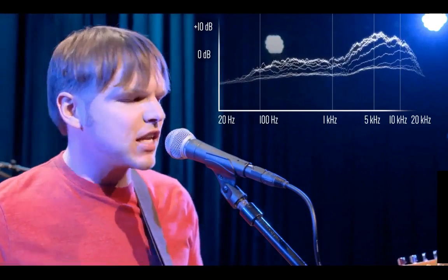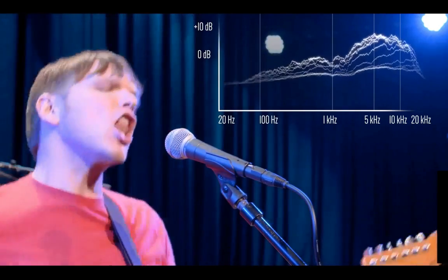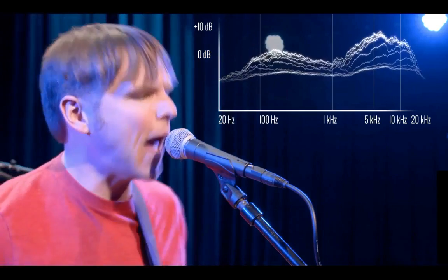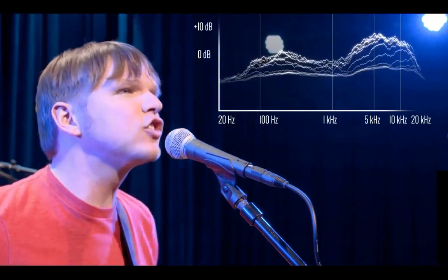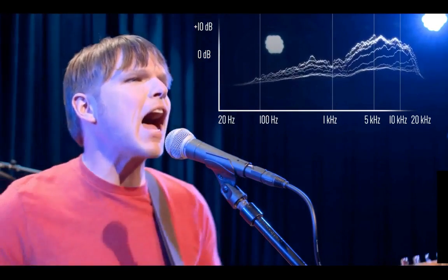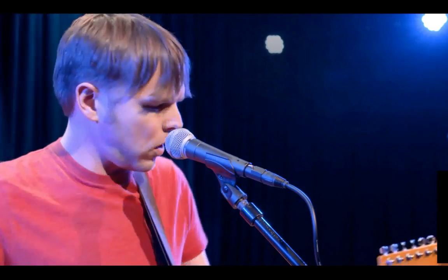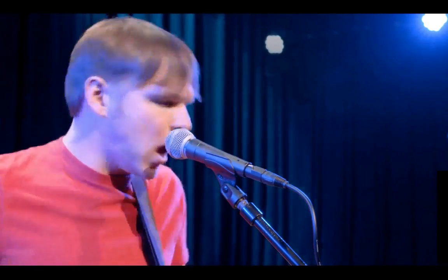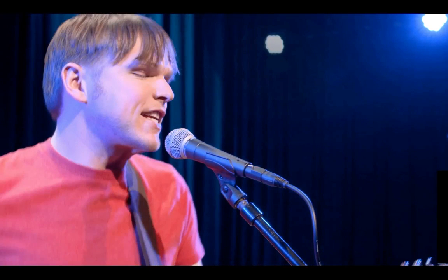You're singing on the mic, you get really close to it, you get this big buildup of low frequencies. You get a little bit further away, it sounds nice and balanced, and then you get too far away and it really is a lot thinner, and you're fighting to get more low end out of the mic. That happens naturally because of the proximity effect, and it limits the user from having a nice, consistent sound quality.